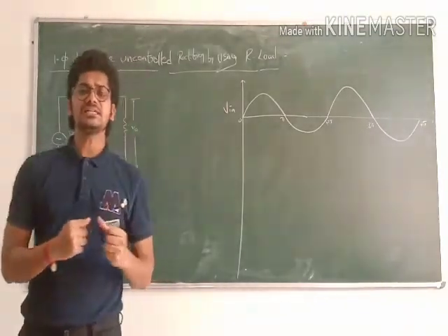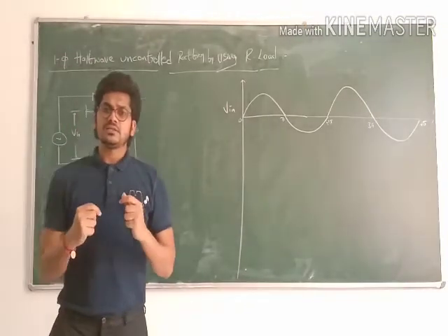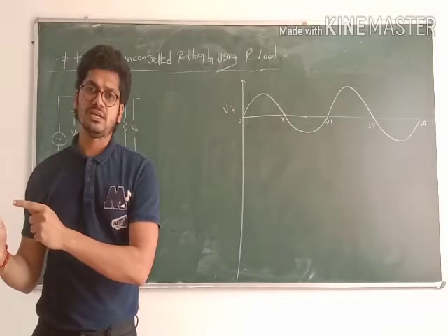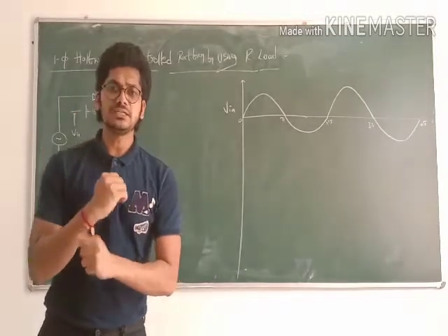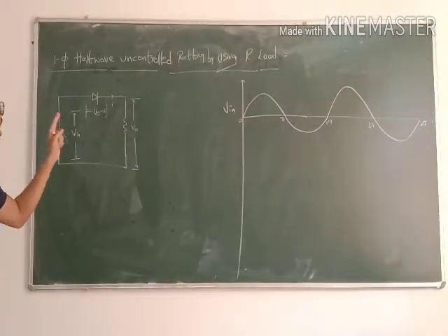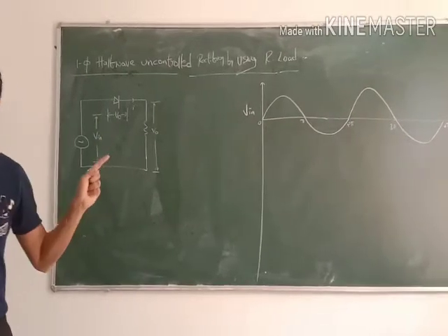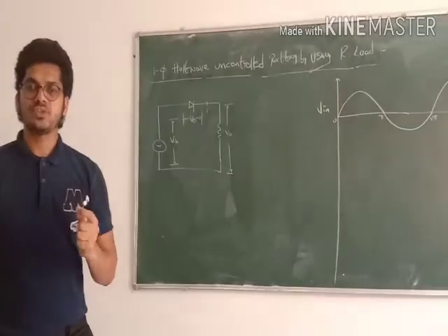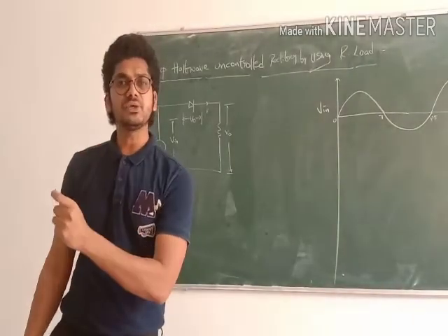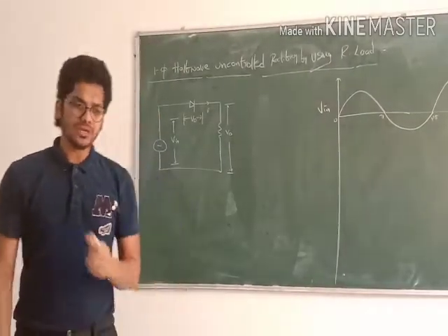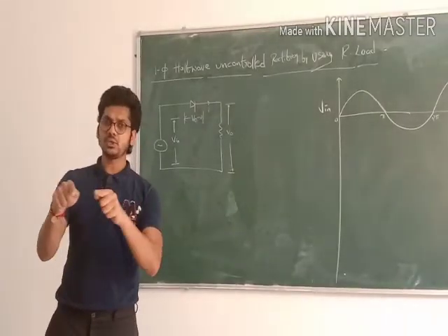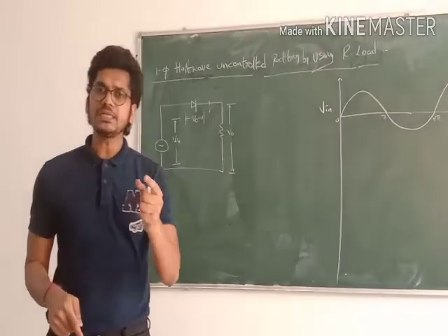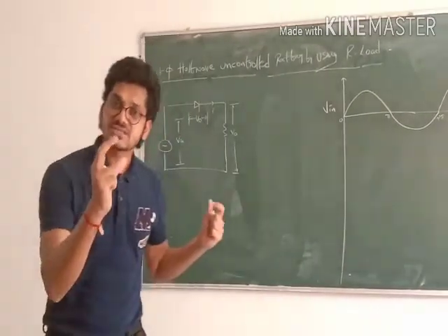The mobile charger is nothing but, as everybody knows, something that converts AC supply into DC supply. Technically, the term is single phase half wave uncontrolled rectifier with R load. Actually, we have three types of switches: the uncontrolled switch, the semi-controlled switch and the controlled switch. What is the difference between them? The uncontrolled switch means the on state and the off state depend upon the circuit condition.